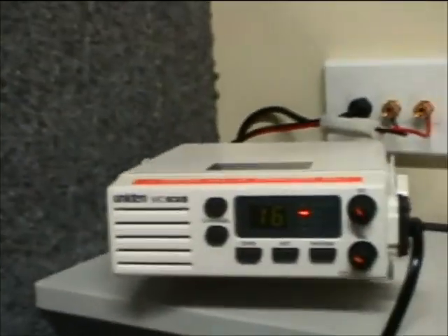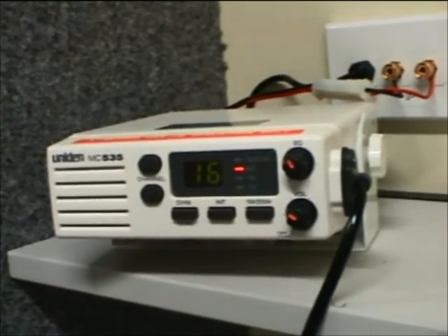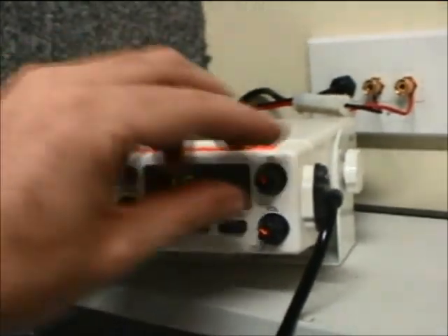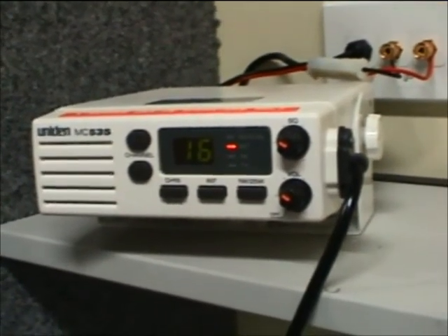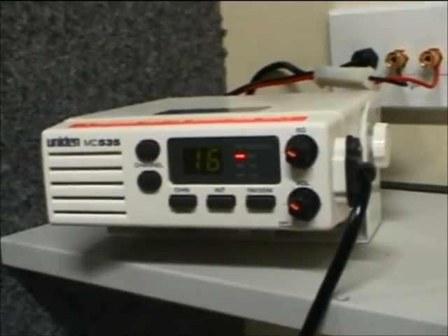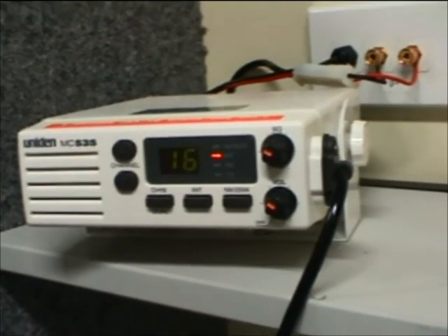Now if you come here to this Marine set, this is running about 156 to 160 megahertz on the international Marine VHF frequencies. It's another FM one there, so you've got the squelch arrangement. And on Marine channels, Marine operators aren't really interested in what frequency they're operating on. They've got about 80 odd channels that are assigned to fixed frequencies.